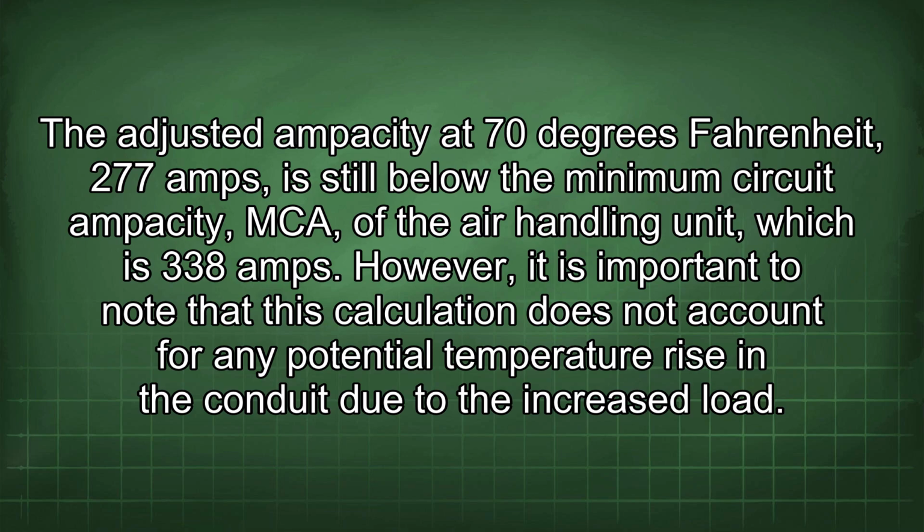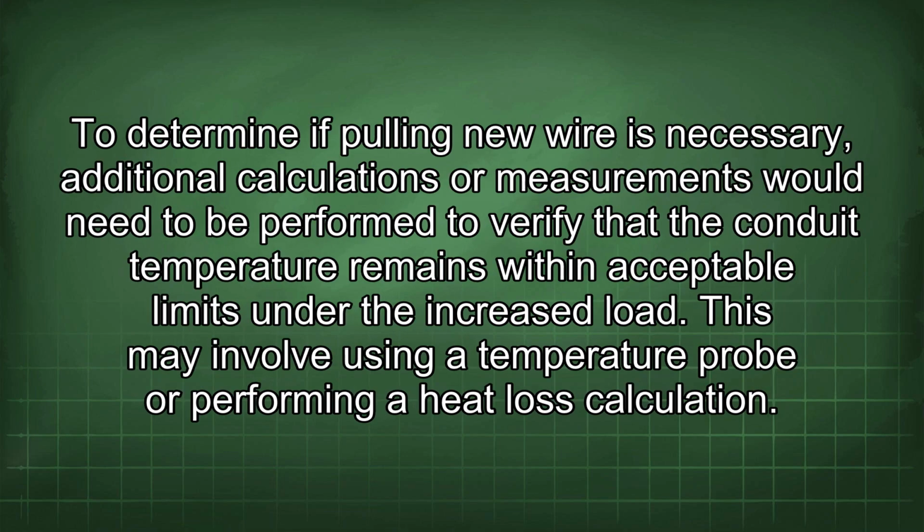However, it is important to note that this calculation does not account for any potential temperature rise in the conduit due to the increased load. To determine if pulling new wire is necessary, additional calculations or measurements would need to be performed to verify the conduit temperature remains within acceptable limits under the increased load. This may involve using a temperature probe or performing a heat loss calculation.